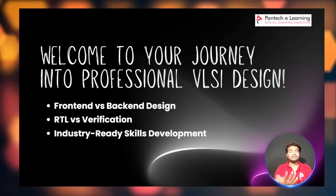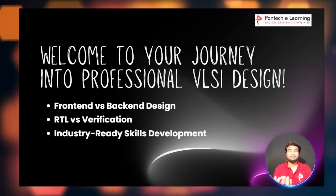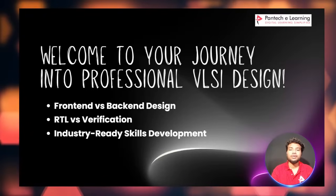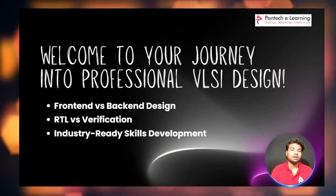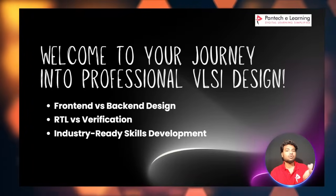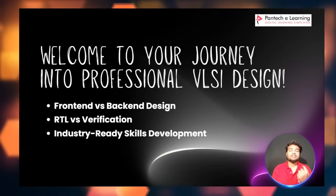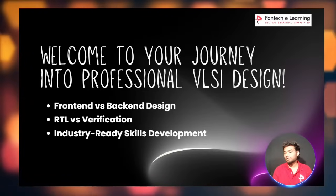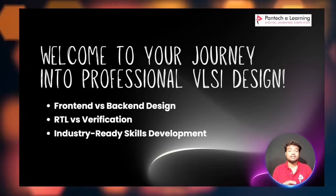RTL is nothing but writing the Verilog or SystemVerilog design code for chips. If you are making a chip like an I2C chip, and you are writing the I2C protocol design code, you are the design engineer. If you verify the design code, you are the verification engineer. This is the difference between design and verification. The design code is called RTL code, register transfer level code.